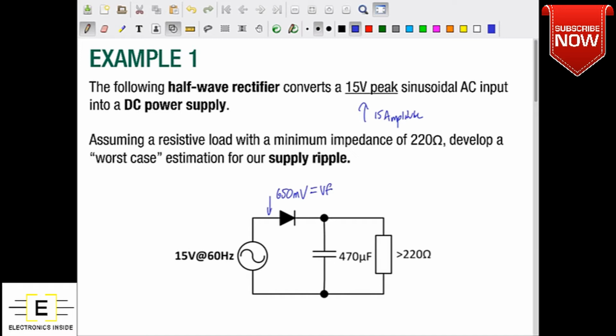In something like an exam, you'd expect to be told a little bit more about this diode, but just looking at the circuit, we can go ahead and take a simple approximation to make some assumptions about this particular diode. It really doesn't change the way the problem flows all that much if we have a different forward voltage. So I'm going to go ahead and assume 650 millivolts.